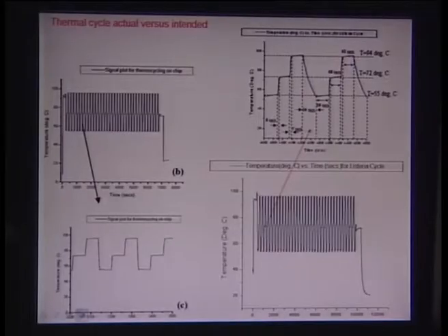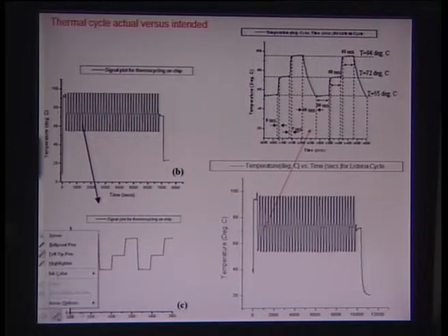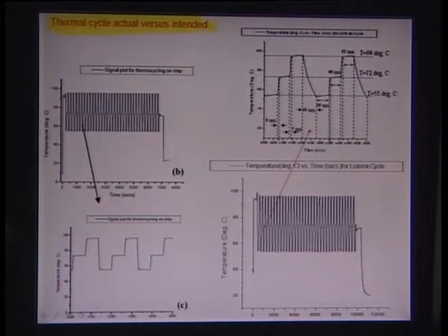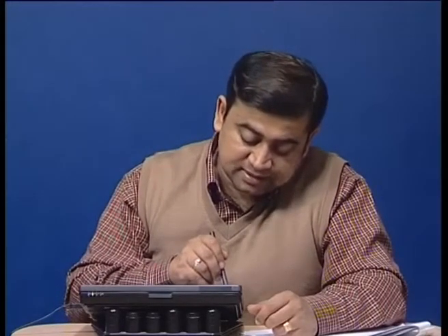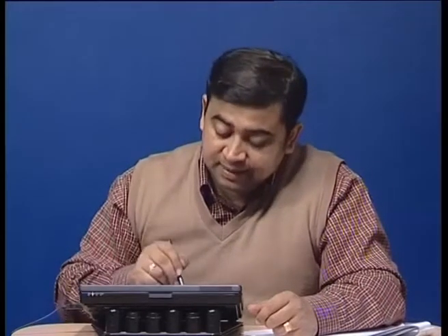Let's talk a little bit about thermal cycling. A very interesting issue here is the time of the PCR reaction, and as we have to rapidly thermally oscillate a certain fluid volume, there is almost always an issue related to thermal management or heat transfer across the fluid. Some of these snapshots, taken from real time signals on microchip PCRs, show how these thermal cyclings can be rapidly varied.